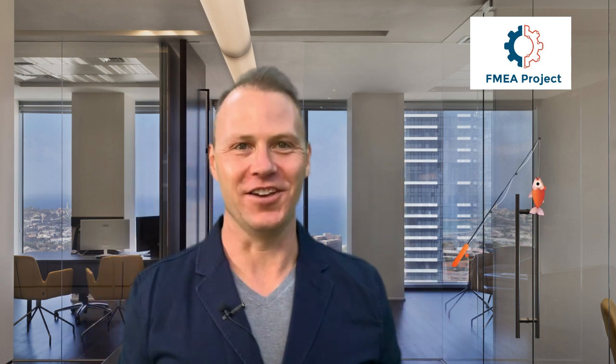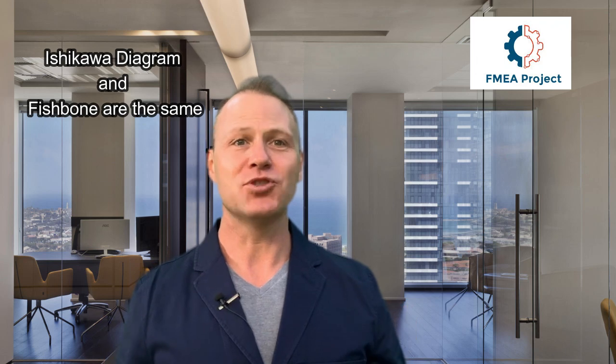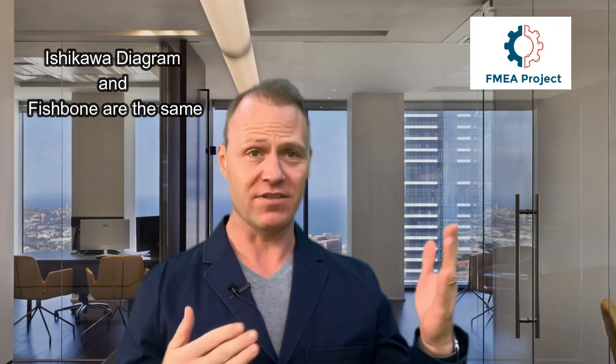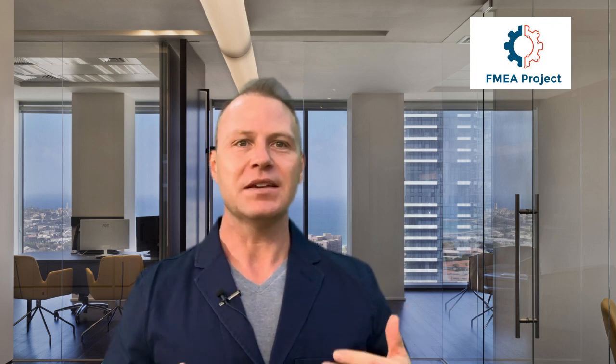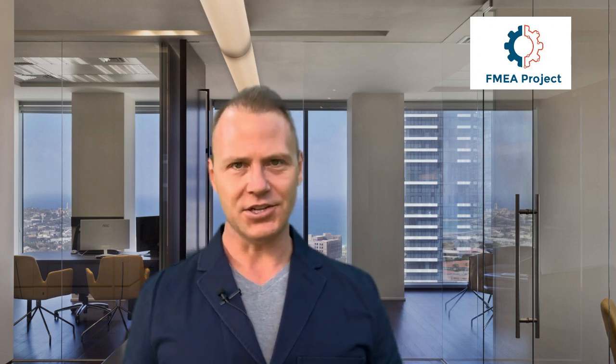We are fishing for failures. An Ishikawa or fishbone diagram is a simple diagram to organize the potential causes of a particular effect. The key word here is potential, not proven yet. The effect that you base them on should be as specific as possible. This is an effective tool in the failure analysis stage.